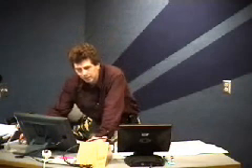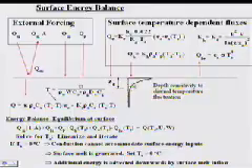I didn't want to have to go through the effort of trying to model all the detail of the within-snow processes. Firstly, because I thought it was complicated, and I wanted to see if we could get away with just keeping it simple. So we just made a single snowmelt model, but we said we're going to allow the surface temperature to be different than the temperature down below, and we're going to use the concept of the depth sensitivity to the diurnal temperature fluctuation. There are well-known equations based on the conduction of heat into a semi-infinite medium that say how deep an oscillation at the surface penetrates.